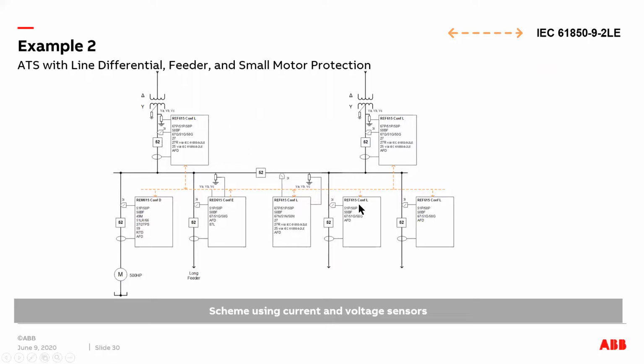So the protection functions can be enabled based on the requirement for each feeder. As you can see here, even though it's the same relay, configuration L, we can use different protection functions for the tiebreaker because it requires additional functions, whereas the feeder relay may not require all the functions used in the tiebreaker. So we can disable all those or totally delete those. So there is a great amount of flexibility in how things can be tied together and programmed in Reliant relays.